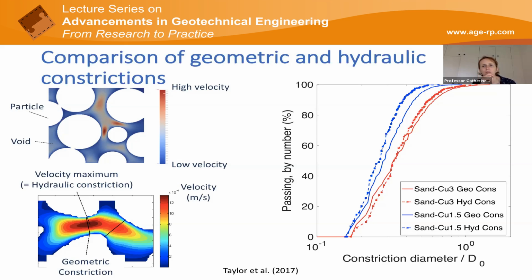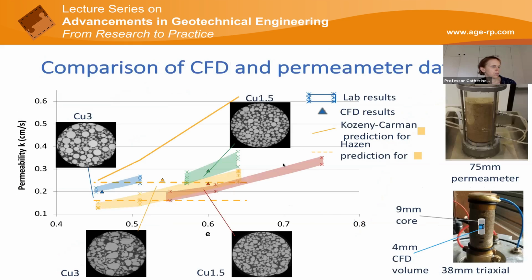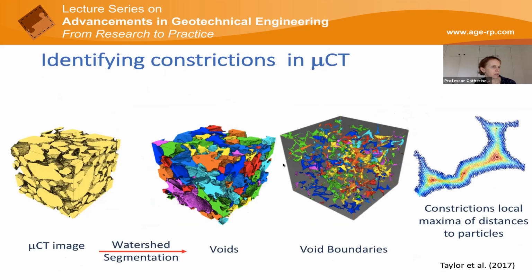Let's take this one. This first comes from Mehrdad from University of Melbourne, and he asks, how could you relate the local maxima in microCT images to the voids inside the sample? So the local maxima, if we go through that again, it's quite hard to get your head around it. We've identified what are the voids. Then we see where, probably here you can see this orange void meets this blue void along this point here.